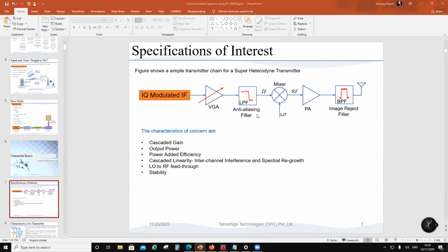Now, when you go to direct conversion, there is another issue. After down conversion, all the information is in the baseband, which is around DC. You cannot have any RF coupling using coupling caps. You have to be DC coupled, so all stages are DC coupled.